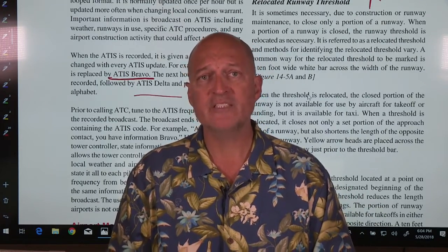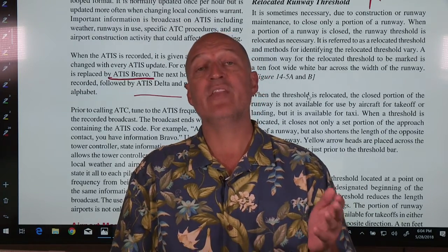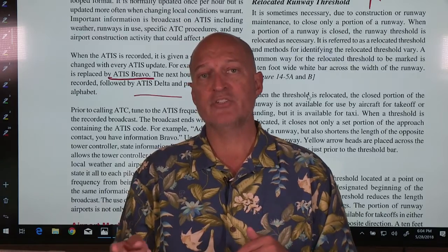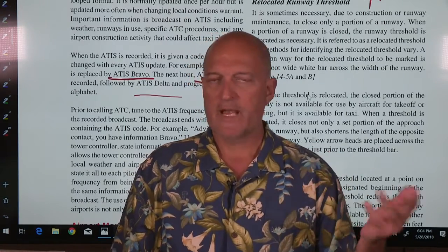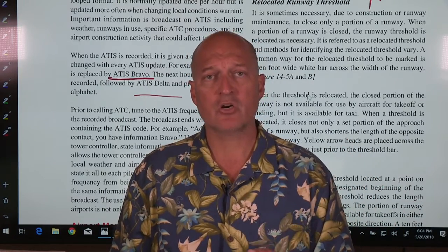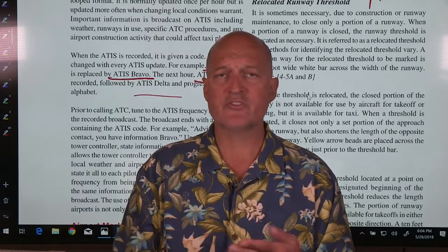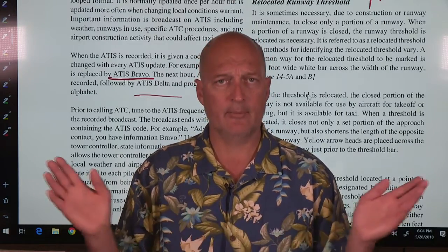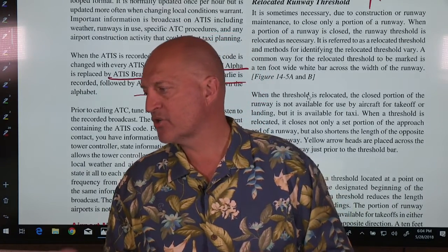If you don't, they may say information Charlie is current. And so then in that case, you'd stand by, listen to Charlie, and then call them back up and let them know Aspen ground, Diamond Star 141 Hotel Lima, ready to taxi with Charlie, so that they know that you know what the current winds are, visibility, sky conditions, temperatures, altimeter settings, and so on. So yes, it is required to use.